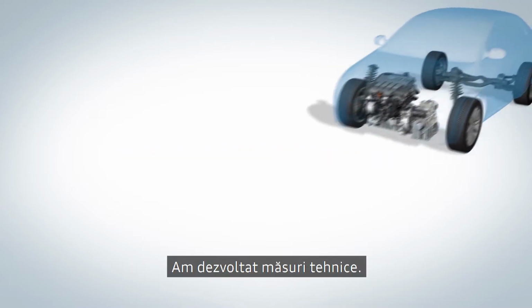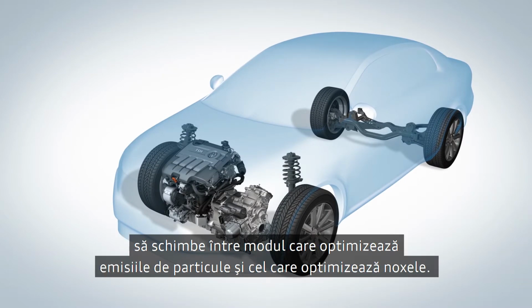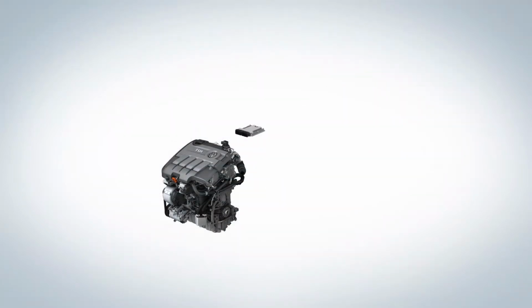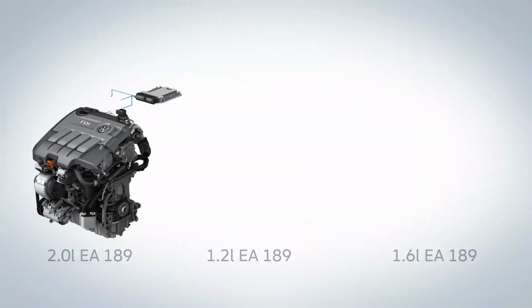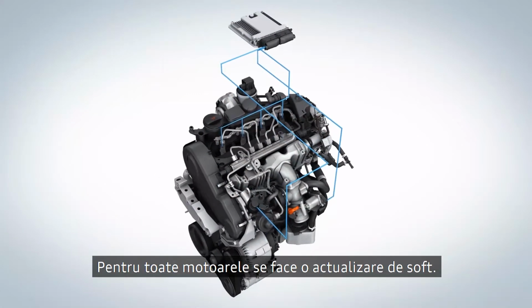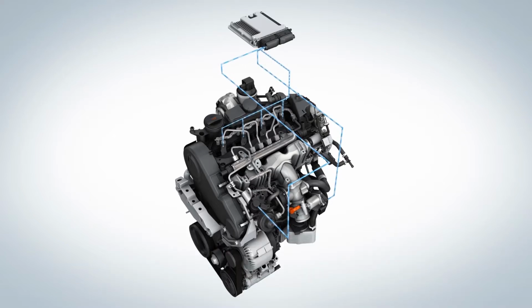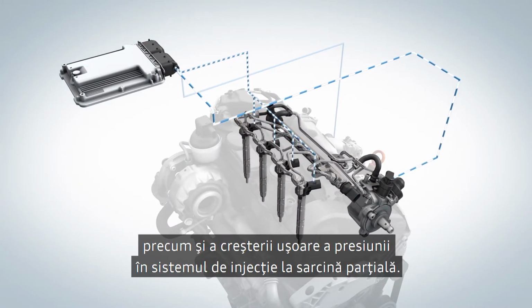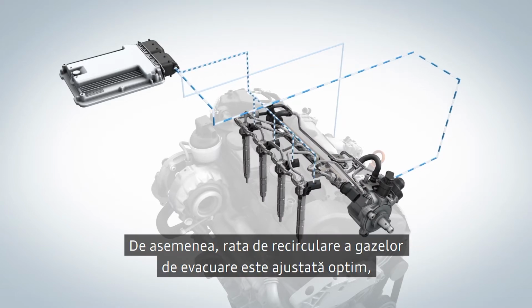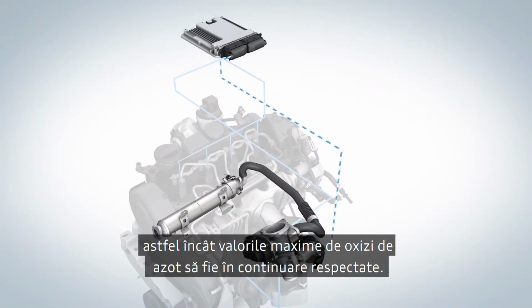We have developed technical measures. The updated engine control software eliminates the switching function that enabled the engine to switch to a particulate-optimized or NOx-optimized mode. These differ for EA189 engines in Europe, depending on the engine type. All engines get a software update. The adapted software ensures that the combustion is always carried out in a NOx-optimized mode. This is ensured by a modified strategy of the diesel injection and a slightly increased pressure in the injection system at partial load. In addition, the exhaust gas recirculation rate is optimally adjusted, which also ensures that nitrogen oxide's test limits continue to be met.